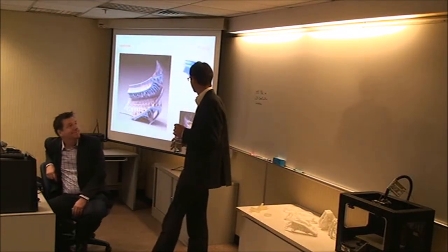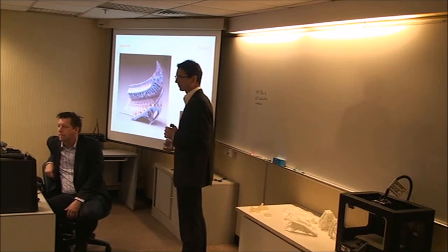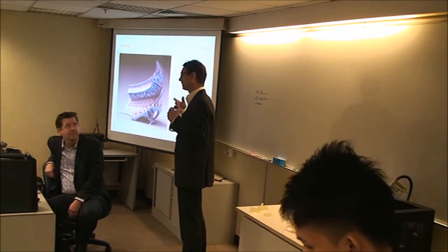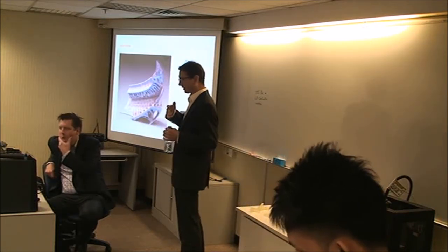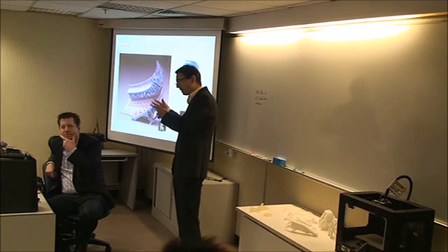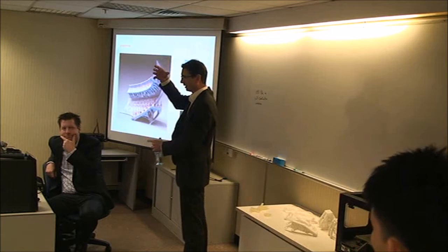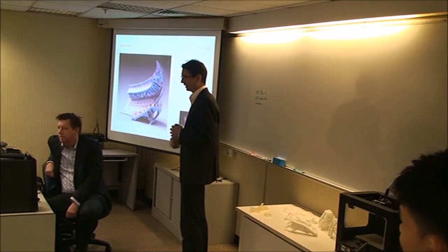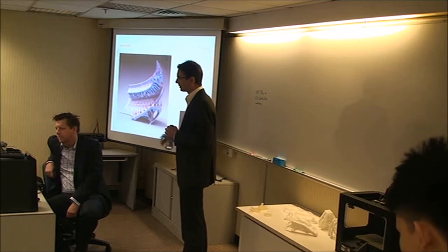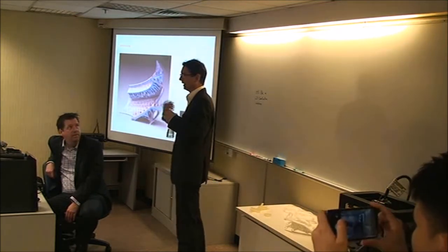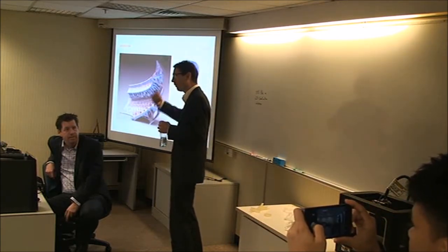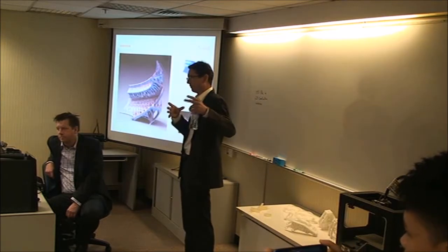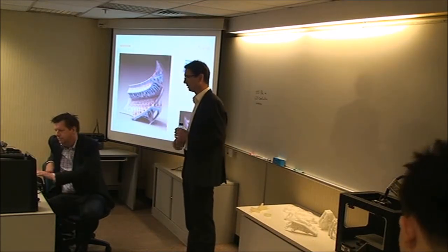Can you analyze the wind load, like in Hong Kong with typhoons? Yeah, wind load as well. We have a CFD tool where you simulate the airflow through a city and derive the loads on a single building. Later you bring these loads into Inspire and run the deflection and stresses. But you cannot calculate the wind loads in Inspire. You can only calculate the response of the building based on the wind loads, so the wind loads have to come from somewhere else, or from a CFD simulation that can be run in our tools using the same licenses.